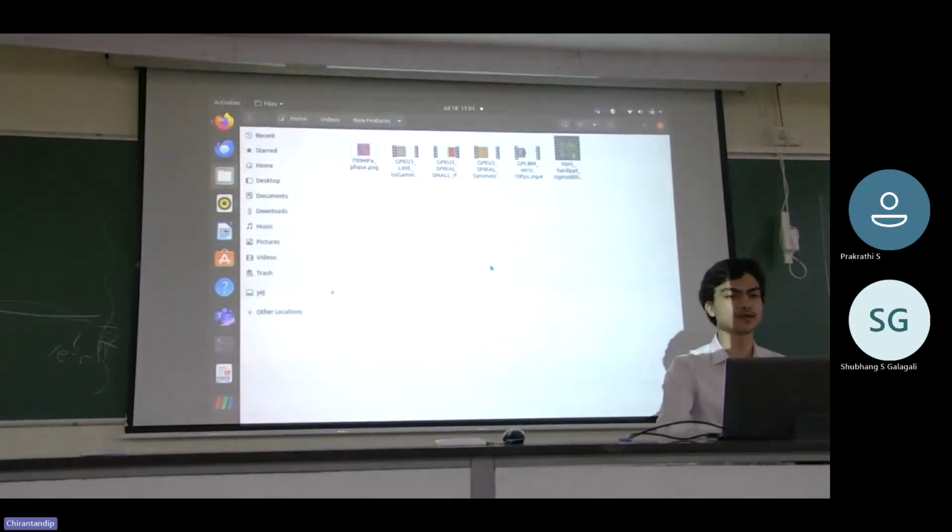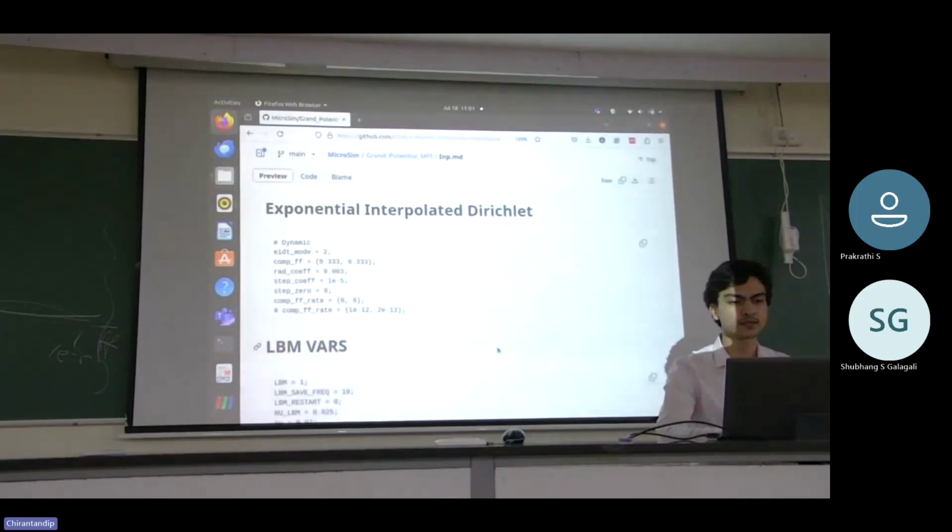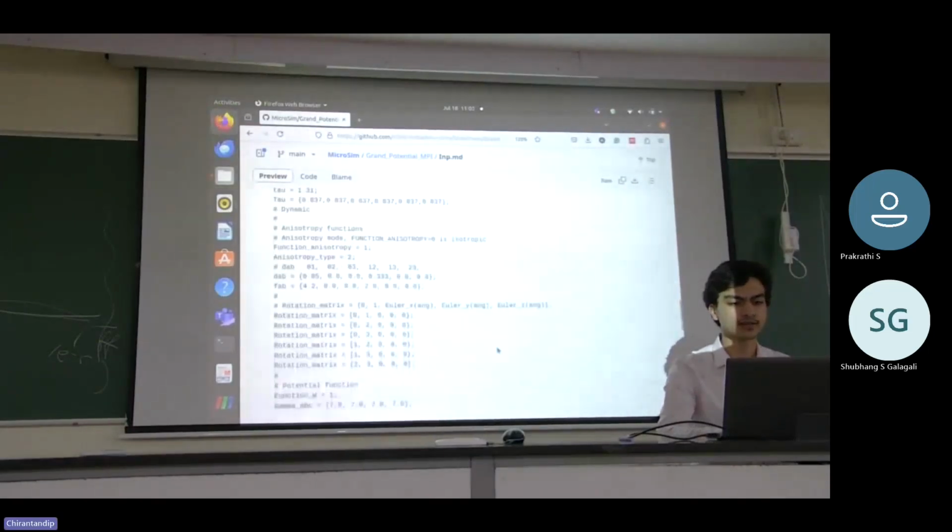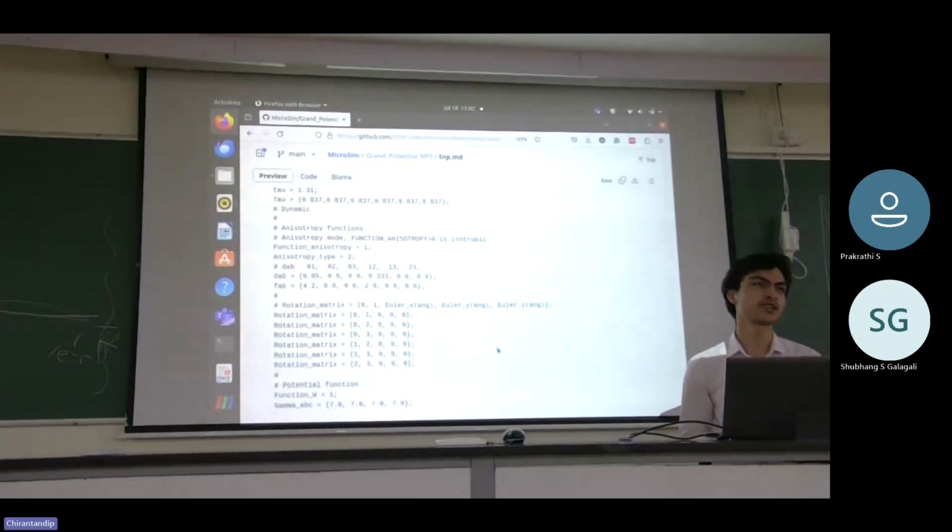One more thing you can do, which is in the include file, is the surface anisotropy. We have added two new anisotropy modules, whereas earlier we had only four-fold anisotropy and isotropic conditions. Now you have two-fold anisotropy about any axis that you want, and there is one four-fold anisotropy about the growth direction, but that can be rotated. So for systems that exhibit two-fold anisotropy, you can orient it and then show it.